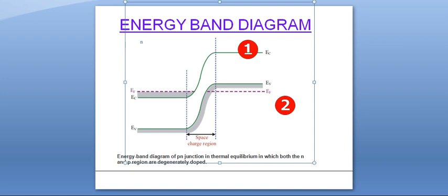When the bias is 0, these lines are at the same height unless energy is imparted to the electrons from some external source. The energy possessed by the electrons on the N side of the junction is insufficient to permit them to climb over the junction barrier to reach the P side. So the conduction band diffuses from the N region to the P region. However, quantum mechanics shows a finite probability for the electrons to tunnel through the junction to reach the other side.